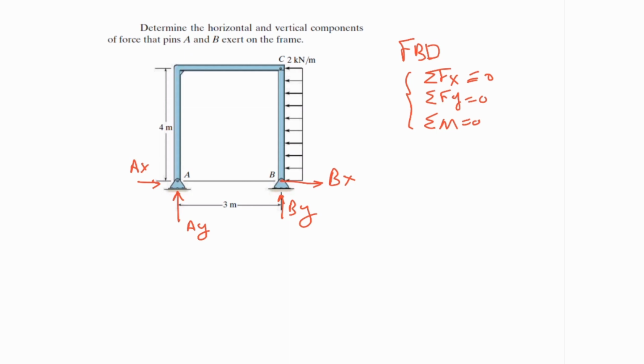When you are facing such a problem, you need to take another look at the mechanism. You may have missed something, like forgetting the idea of finding the two-force members. If you look at this member, we have the conditions of a two-force member. What was that? We need to have two connection points, which are A and C here. We don't have any external forces or moments applied on this link, and also the components are massless. It's not mentioned in the question, but it can be assumed as long as they are not mentioning any weight for the links or any density for the links. We can assume that they are massless, meaning that this is a two-force member.